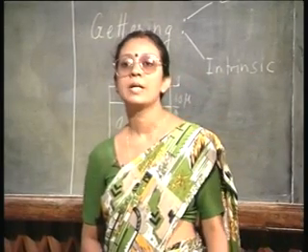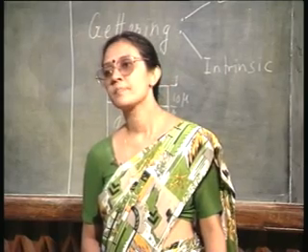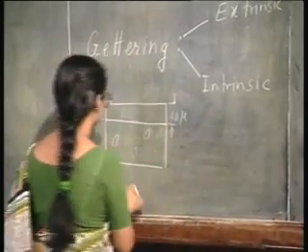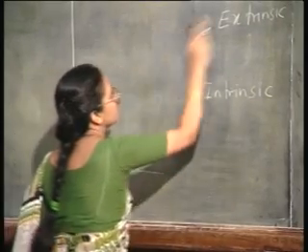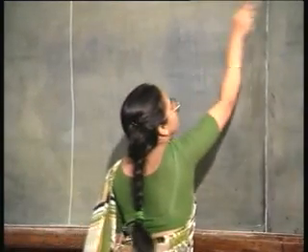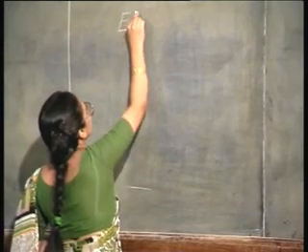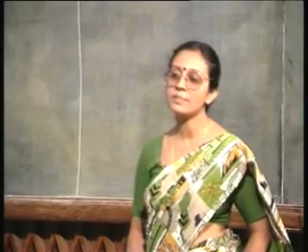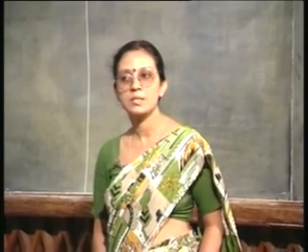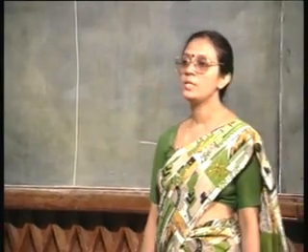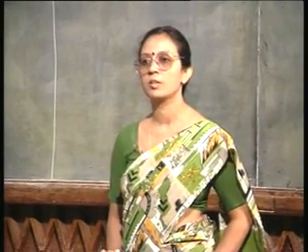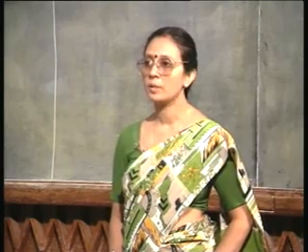For that, you have to use epitaxy, which brings me to the second processing step after crystal growth, that is epitaxy. Actually, epitaxy is a combination of two words. Epi means upon and taxis means ordered. So, the meaning of epitaxy is simply juxtaposing these two words: ordered upon. What is ordered upon what? That is, the epitaxial layer is arranged or ordered upon the bulk crystal.